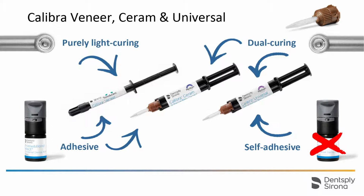Two components are always required for chemical curing that must come into contact with one another to activate the curing mechanism. You can recognize that a cement can at least be chemically cured by the fact that it is supplied in the double barrel presentation. As said, you will find the same variety of curing modes and adhesive mechanisms among competitor products.